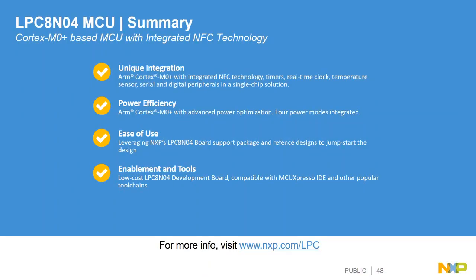In summary, we have explained the main features of the LPC800. We feature a unique integration. We have the Cortex-M0+ with really good power efficiency, and on top of that, we have the NFC tag. We also have the timers that you usually find in the LPC devices. We have a real-time clock counter, temperature sensor, GPIOs, SPIs, I2Cs. So it's a really well-integrated single-chip solution. Thanks to the Cortex-M0+, we have really good power efficiency, 4 different power modes integrated into the LPC804.